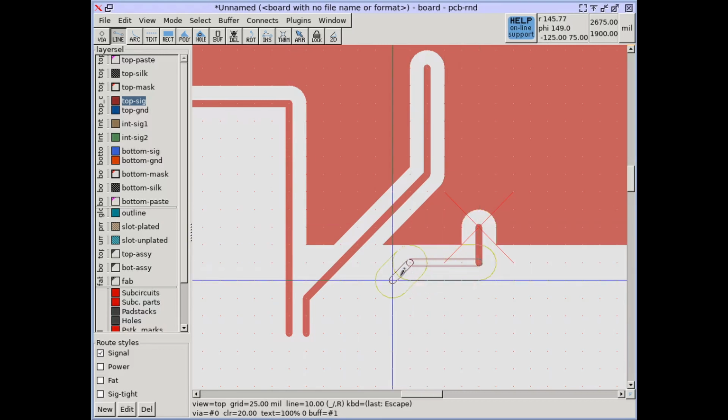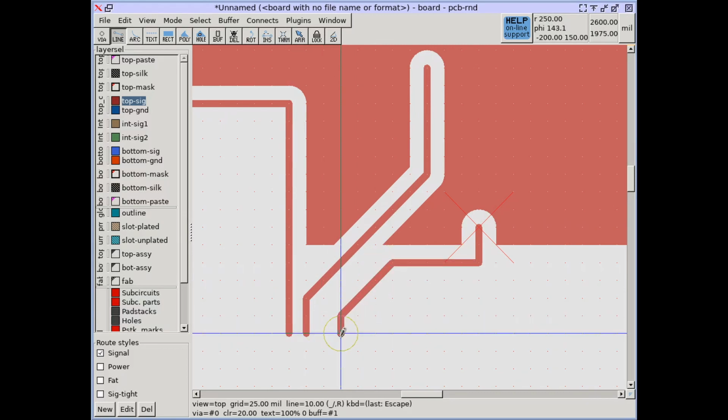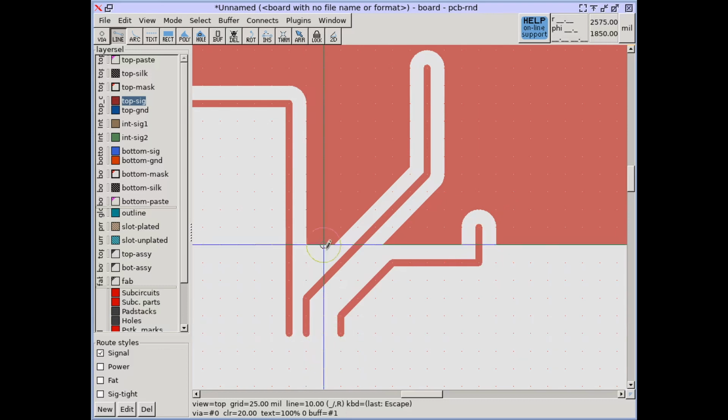When routing inside a polygon, the indicated clearance is exactly what is then cut out of the polygon. When drawing in proximity to other objects, the indication helps deciding how close the routing could go.